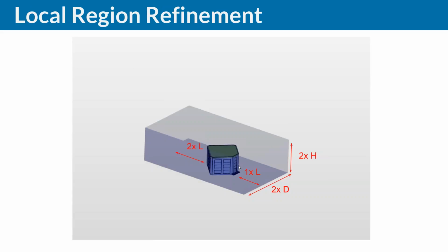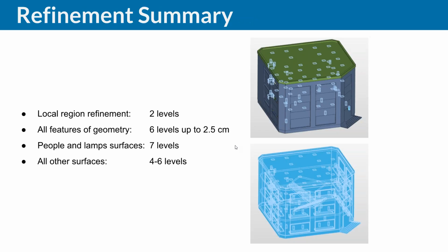Inside our control domain, we also defined a refinement region, which means that this region, the linear region around the building, will be resolved and calculated with very high precision. Because some people ask a little more about this, as I mentioned, meshing is very important, because meshing in the end defines where you will use which accuracy for calculating the simulation result. A level means that we will double the resolution.